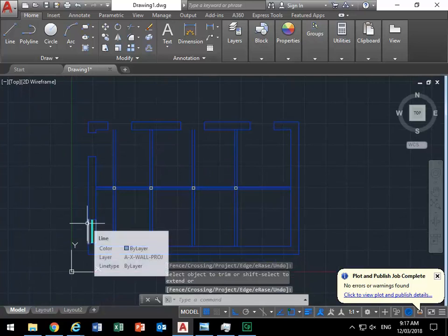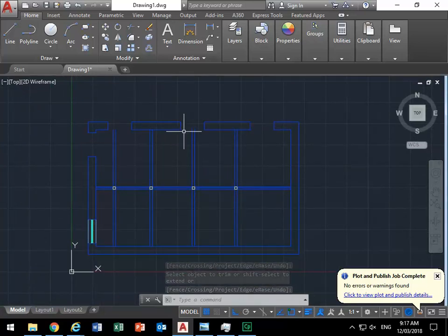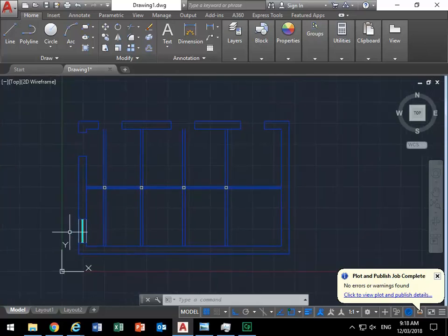But the key there is that I've put in the openings first before trying to draw the windows. And that's where I think people create a lot of work for themselves by doing things in the wrong order. And again, putting the openings in first makes it much more efficient and also logical in the way that you set things out. And so it's also going to relate to the design process, because you shouldn't be trying to document and design your windows. All you need to do is give an opening size. So that's what I've started with there.